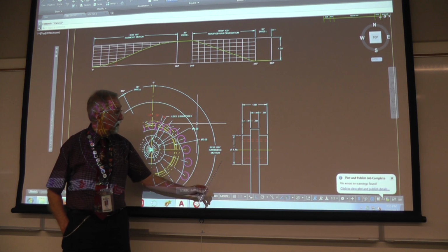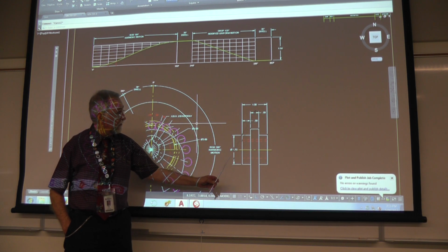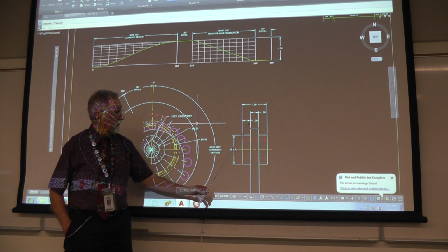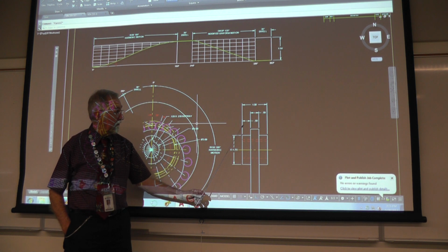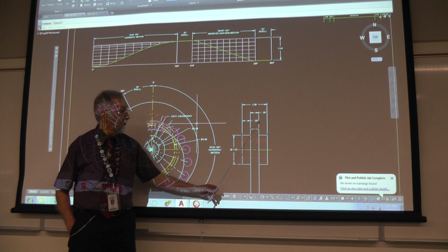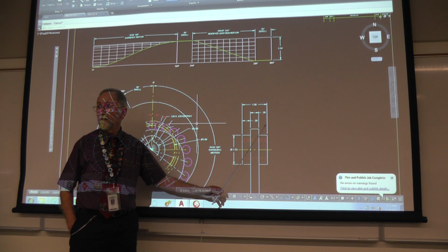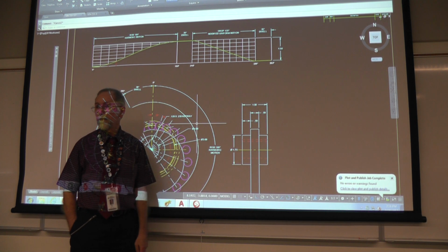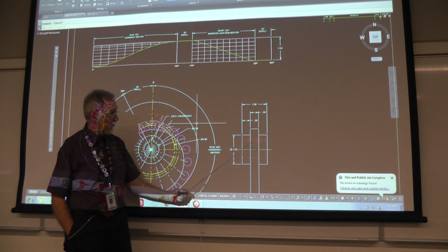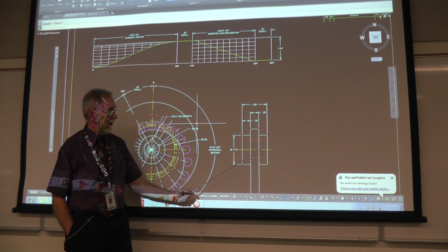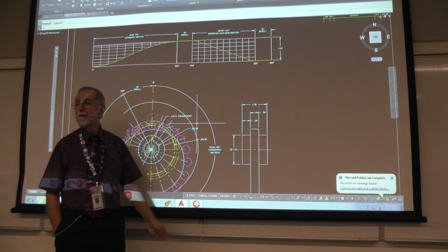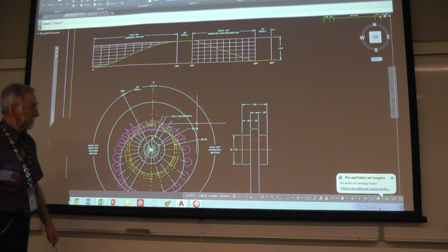So this is 1/2 inch. This is 1/2 inch. The plate thickness and the amount that the hub protrudes out, we do not put the third dimension in here. That's superfluous. So that's the dimensioning that's required. Don't forget hidden lines, don't forget center line in your side view.